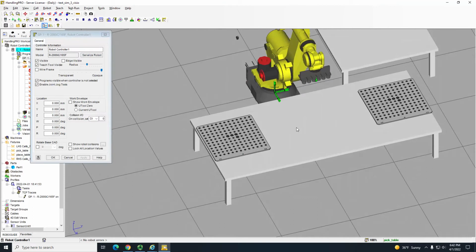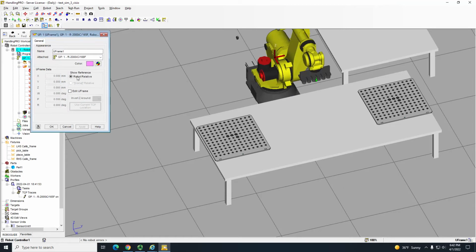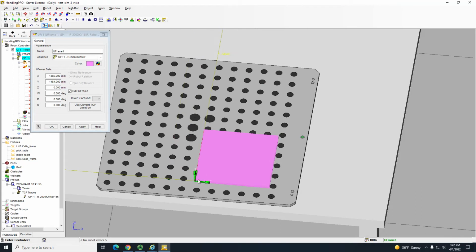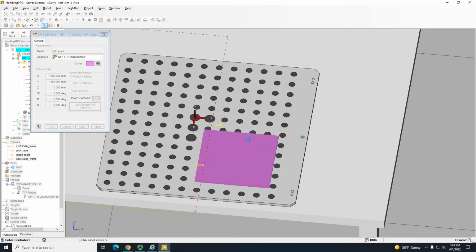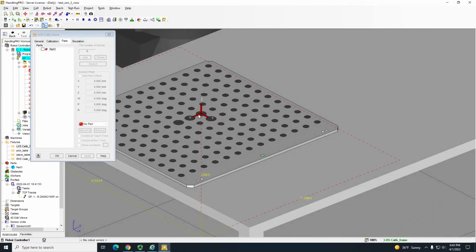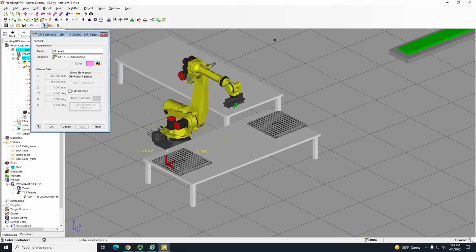And you see this blue box. It kind of shows up somewhere. You don't want to move the robot. Double click on this one. Edit U frame. Move this box. So first things first, we need to align our axis of the user frame and this. So this is X, this is Y, and this is Z, right? You see this? X, Y, and Z. Same way, I want the axis of the user frame to be aligned.